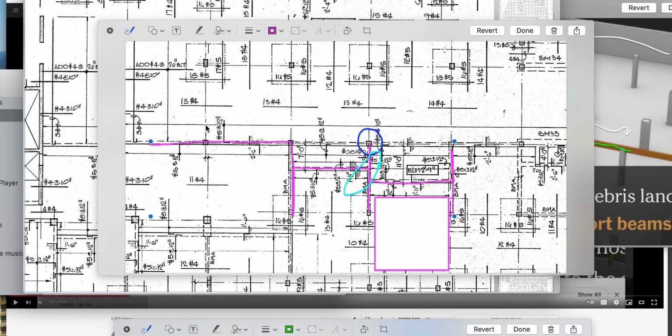This distance is approximately 20 feet. This is the front of the building. This is I, K, L, and M. This is a step down, as you recall. It's a 1'6" step down. It's that drop slab detail. So it does that move like that, and that's 1'6" here. And it's probably got a cold joint right about here, I'm guessing, because of what we saw under here. So they built it consistently that way, perhaps.